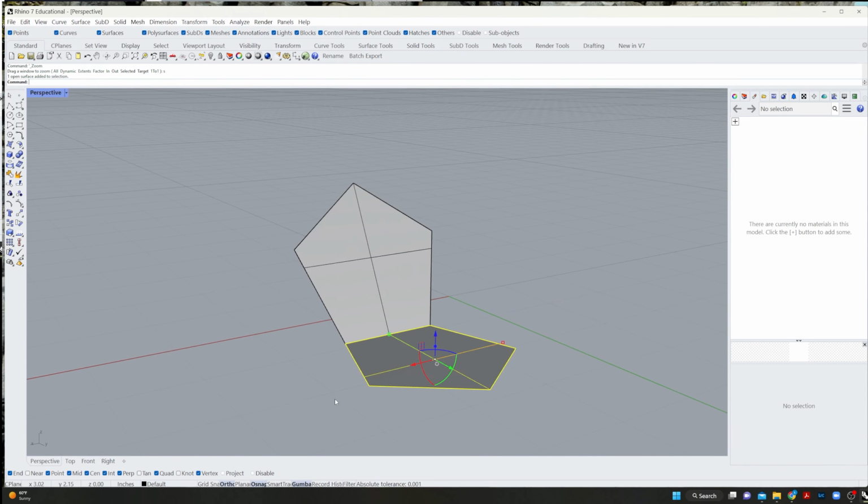Those measurements are the draft angles for a dodecahedron. I just looked it up online, and geometry, great. So we'll do it again. Enter brings up that same command. Rotate 3D, select my object, enter, angle from there to there. Then I can just hit enter to use the same measurement, and enter again to get out.